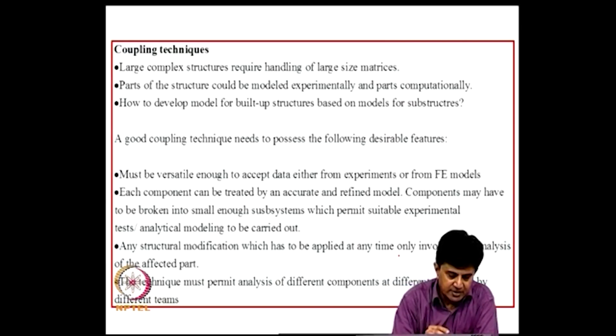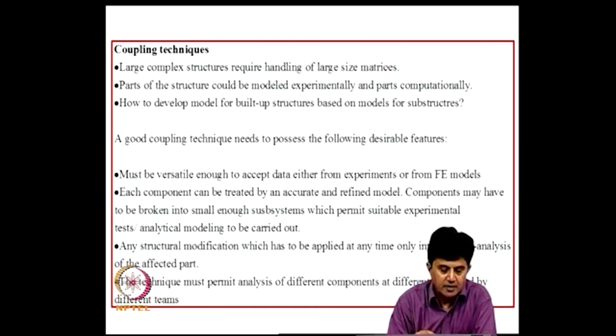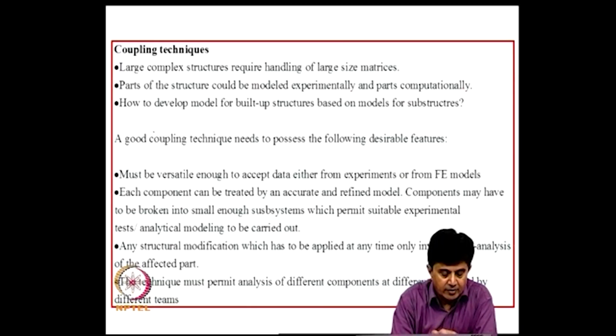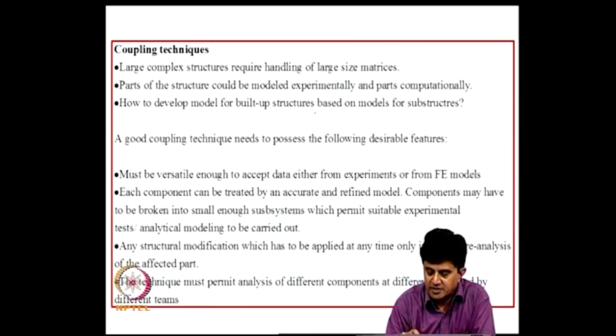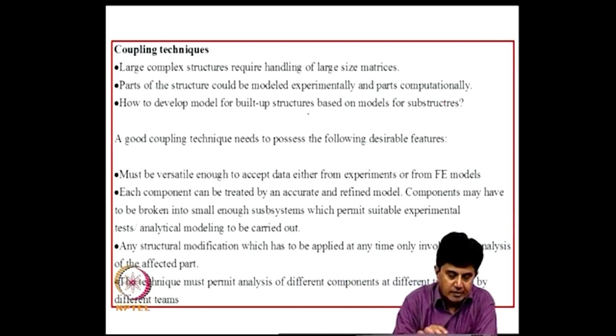Again, this is a device to treat large complex structures, and the problem is that large complex structures require handling of large size matrices. So, can we do something about that? Similarly, in a manufactured product, parts of the structure could be modeled experimentally and parts computationally. Now, the question is how to develop a model for built-up structures based on models for these substructures. The coupling techniques answer these questions.